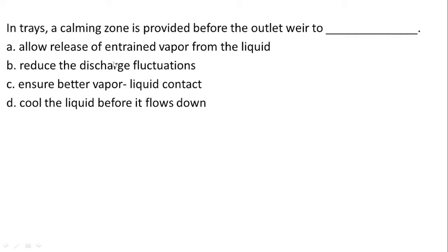Entrainment flooding happens when the vapor entrains a significant amount of liquid along with it, mainly due to the increase in vapor velocity through the sieve. Downcomer flooding is due to the increase in liquid velocity. With increase in liquid velocity, the height of the downcomer backup will increase. This will cause the downcomer flooding.